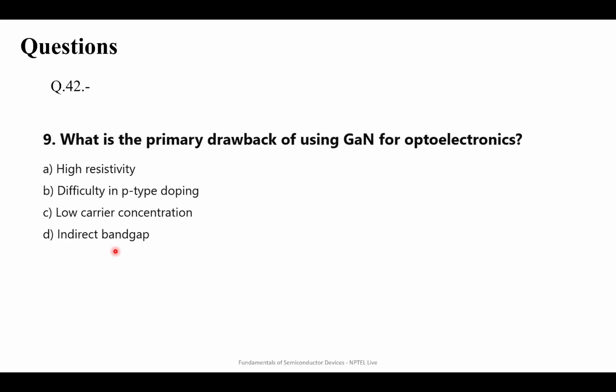Sir, explain this please. Yeah, so I was writing. You should check what band gap values for aluminum nitride and gallium nitride you are using to solve this question, because the values can slightly vary. Aluminum nitride can be 6.1, some can write 6.4 electron volts. So the values that you are using are very important.